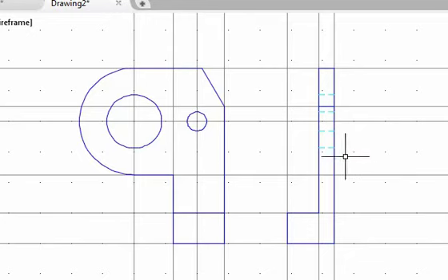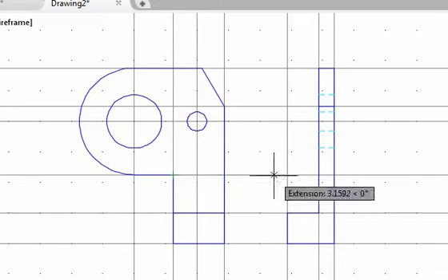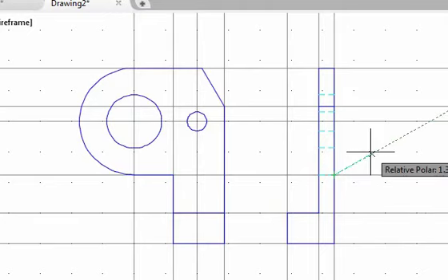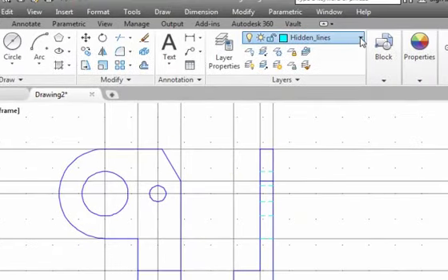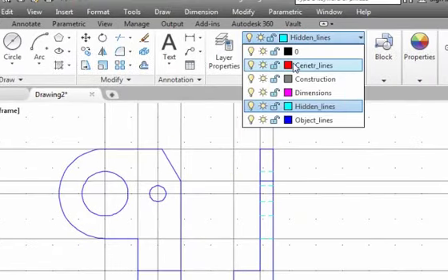The Auto Track feature really helps this type of construction. We need one more line showing the underside of the circular feature. Hit the spacebar once to end the command. Next, we will create the center line in the side view. Set Center Lines layer as the current layer.